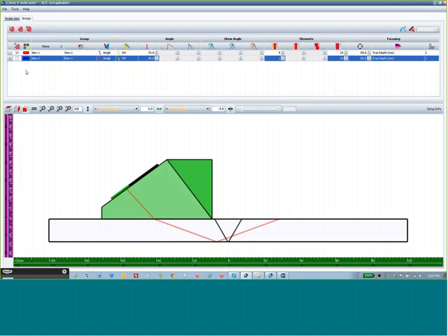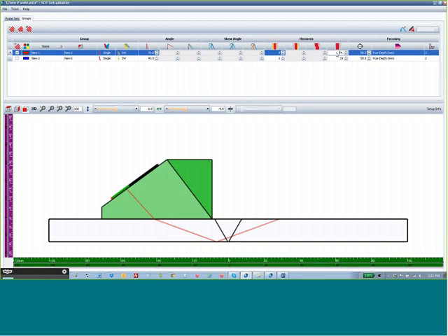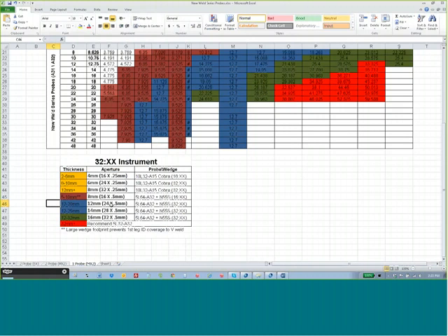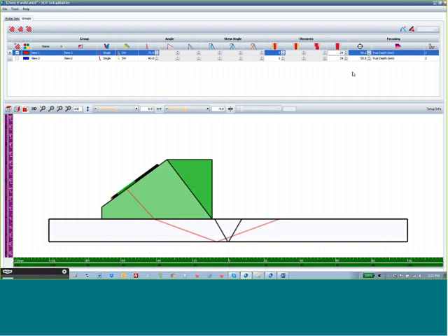Before we go to the compound S-scan, I would like to demonstrate the back and the near and far side of the compound S-scan we're going to create by first selecting a 24 element aperture. This came from a chart based on thickness and probe and within the ANSI piping range that we will recreate in the Setup Builder. This is always decision one. The size of the probe or its beam relative to the weld bevel and sound path is our first decision.